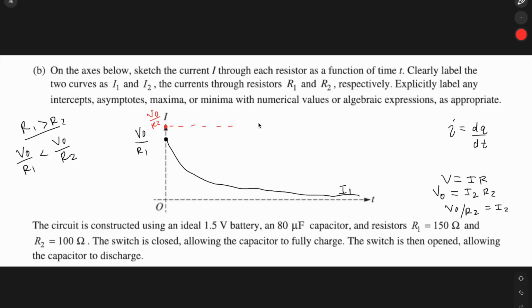We have our current. And important to note here is that our current actually is not changing in this situation because it's being held constant because it's just based on Ohm's law. In our RC loop, like the loop that contains the actual RC circuit, our current is going to be changing because we're charging the capacitor, and the capacitor gaining charge is actually going to be affecting the rest of the circuit.